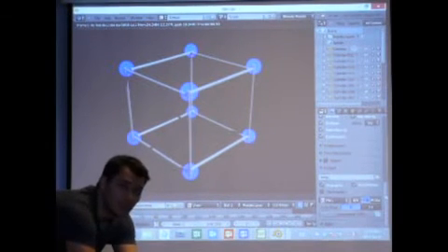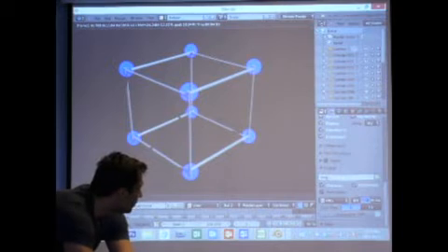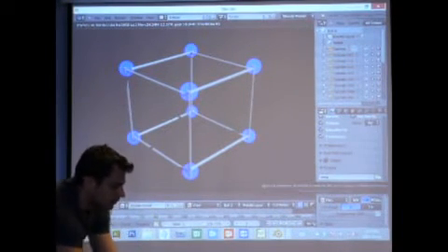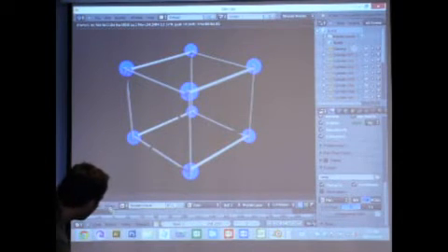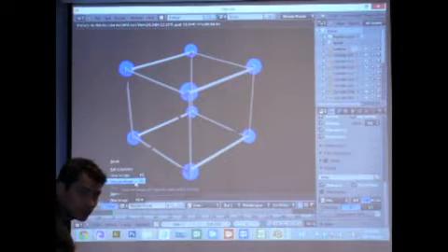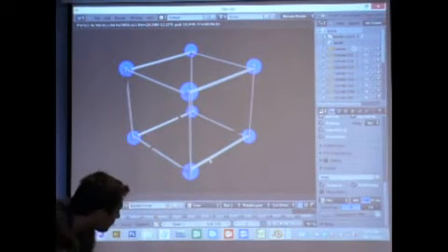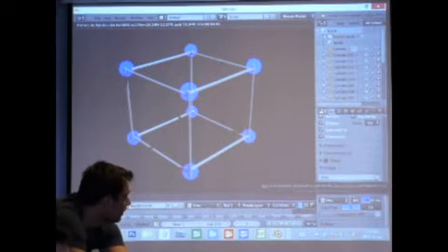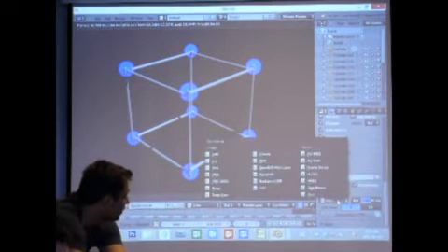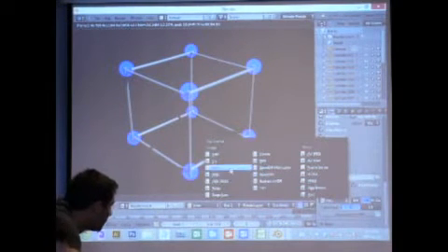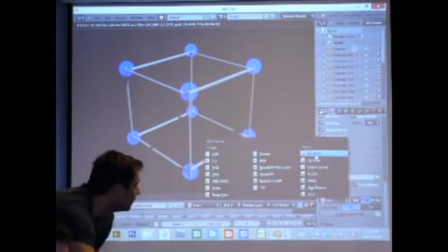Right at the bottom, this is our output, our portable network graphics. This is the file we're saving it as, in a temporary folder. But since we can actually just go to image save here or press F3, you can just save it directly from here. But you can also choose the output folder here. You can change the type of export you want to do: JPEG, bitmap, videos.